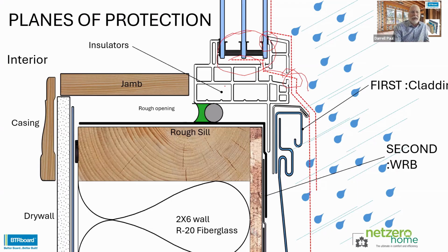Now, with these little cavities, these little compartments that we see, those are actually little insulators. Those are no different than your fiberglass insulation. You're compartmentalizing that dead airspace so that when there's convection in there, it's not moving from one side to the other, right? Not from the cold side to the warm side. You've blocked those out. So fiberglass does the same thing. It just makes smaller compartments.